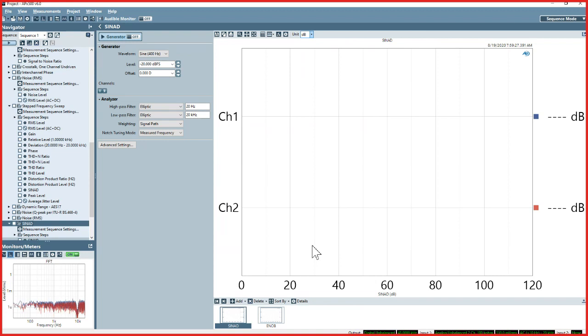to the device itself. So one that I'll say comes up the most frequently is when we're looking at delta sigma modulators. There is, to our knowledge, no delta sigma modulator that can be fed a full scale signal without becoming unstable.